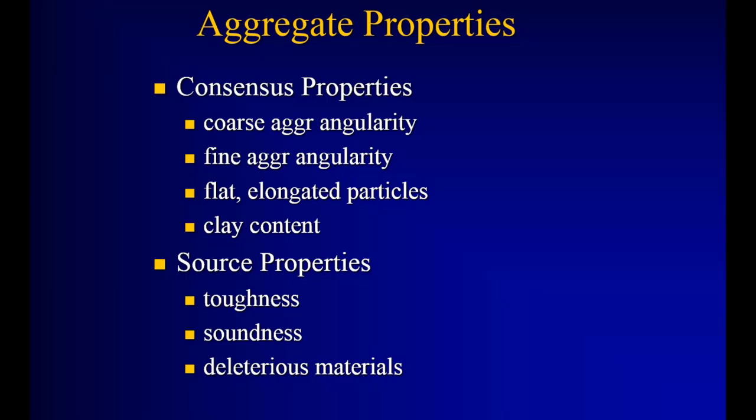So plus number 4 material is considered coarse aggregate or rock, if you want to call it that. And it's all the plus 1/4 inch. In fact, it's slightly a little less than 1/4 inch subtracting the diameter of the wire in the sieve. So 4 openings per lineal inch minus the diameter of the wire in the sieve. So all that plus 4 material or coarse aggregate material, you run a fractured face count on it.